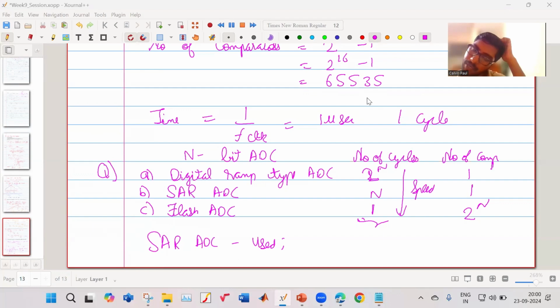I see, voltage compatible. I didn't understand these logics, these ADCs and DAC and this counter, etc. All these work in a way to control your power electronics. To run your power electronics, you need all these sort of ADC and DAC, etc., and the counters, to generate what duty ratio or what gate signal I must give to my power electronics converter so that it will run. Okay.